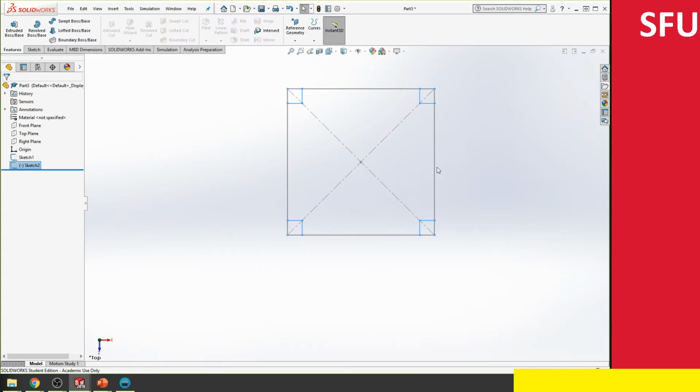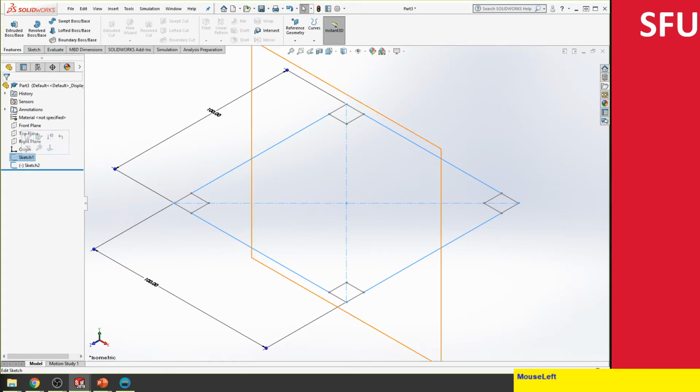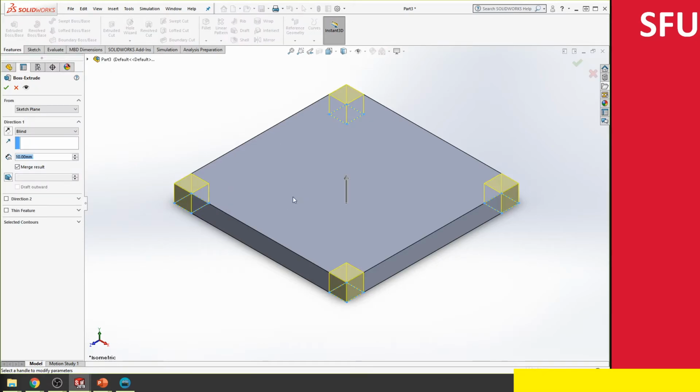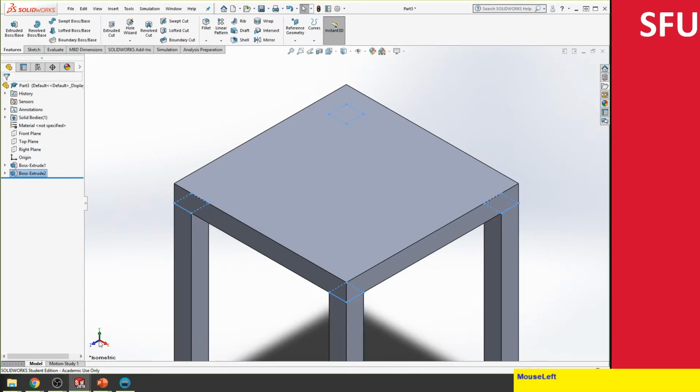Then let's do Control 7. So we want the tabletop to go up maybe. So let's click on that and say extrude. So this looks like it's set to 10 millimeters. That sounds good. And then we look at the other sketch, and then we extrude. And so this, we obviously don't want the leg going into the table. So we're going to flip directions, and then maybe we'll make this about 100 millimeters. And then we say okay. And then this basically creates a table by sketching on the X, Z or the top plane.